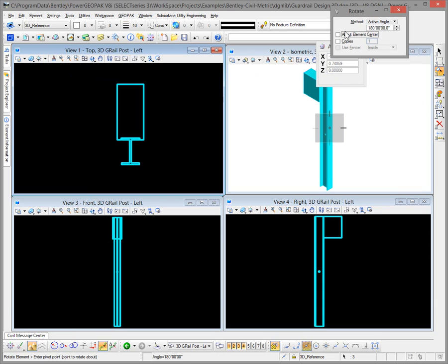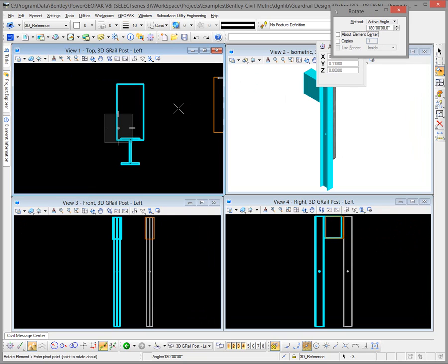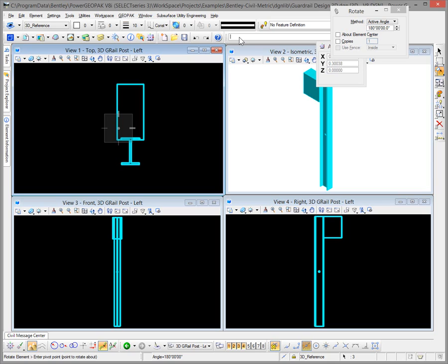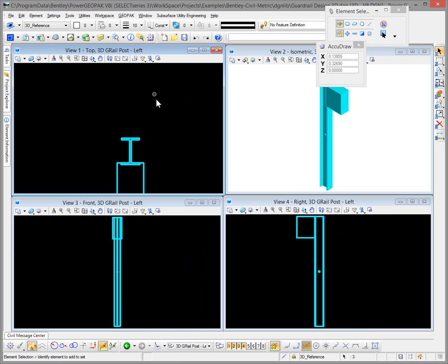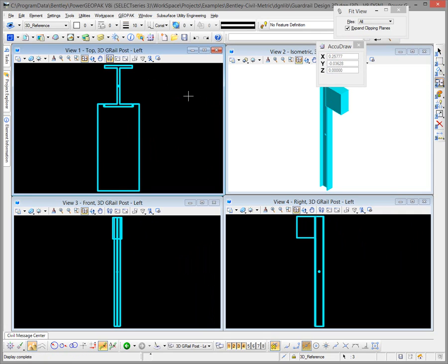So just type in 180, enter. And when it asks us to basically enter a pivot point, I'm going to put in xy equals 0, 0, 0, enter. And then I just do a reset, and now we have everything flipped 180 degrees.